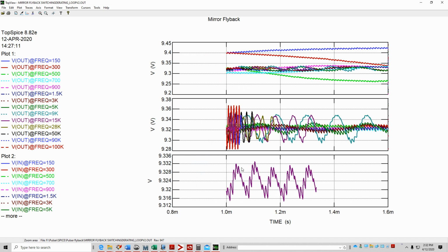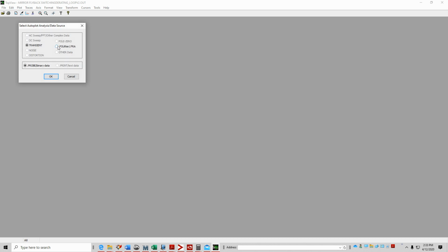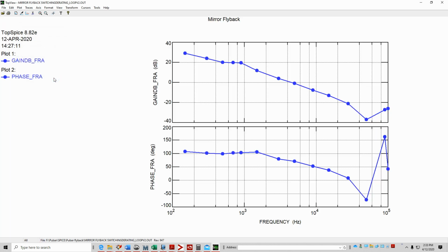You can see the ripple, and it looks like a little sine wave. But if you start seeing that it looks like a triangle, a severe triangle, then you have too much distortion, meaning that you have too much signal, and you may have to run the simulation with a smaller voltage test signal. Anyway, that's a pretty neat feature that you can look at the transient that way.